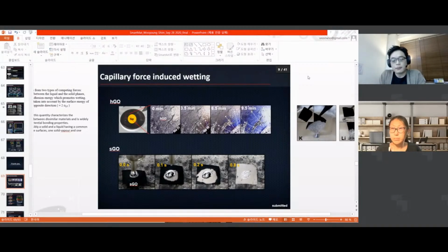So the first thing is, if you want more resolution, let's say you want to compare it to EUV and go down to the 10 nanometer length scale, the first thing you need is a 10 nanometer mask, a mask that has a 10 nanometer chromium pattern. That's one issue, because all the patterns you define on the mask are done by e-beam lithography first, and then you use that mask as the optical technique. I think that's the first.